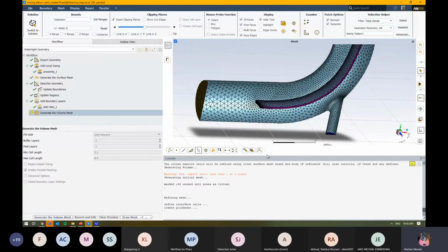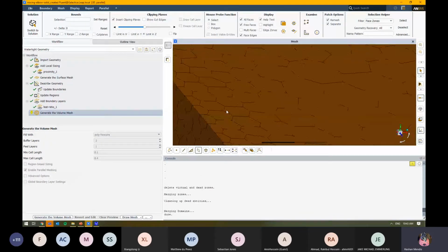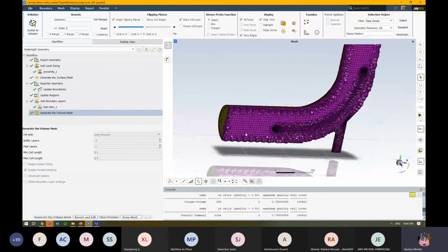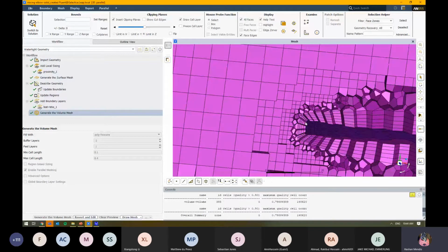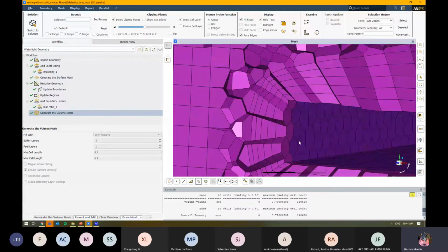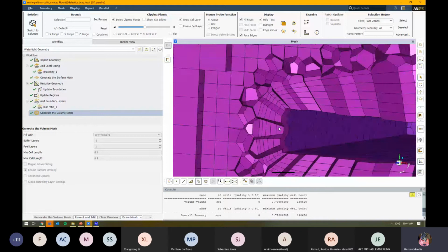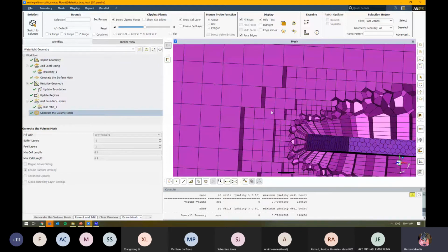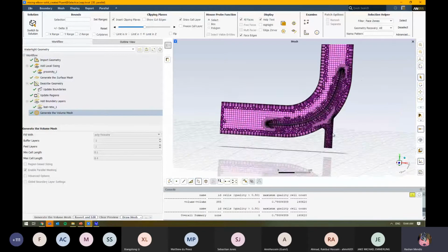Right, and it'll go through the steps of making it. So 1 millimeter might be very, very fine. We'll see what we can do there. So you can see now it's generated a finer grid. We've got more elements. It's converted it to polys, and we've got the hex core region around there as well, right? We can see where we've got these jumps around some of these regions as well.